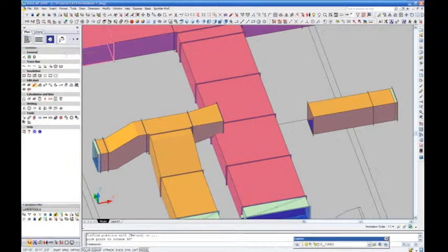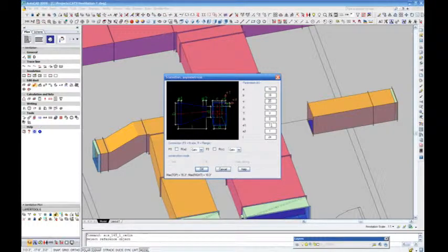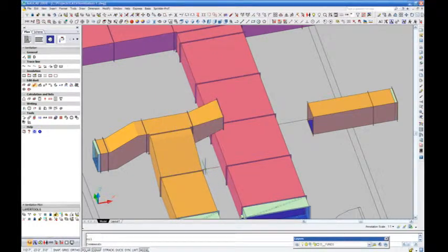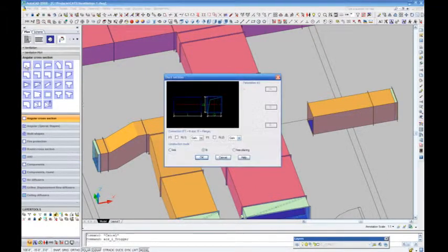In the CATS Commander, we will select again the Redimension Part command. We will revise the T dimension, adding 4 inches. Select OK and the offset now clears the supply duct. We will now add a straight piece of duct to the offset. We will add a transition between the remaining unconnected parts.